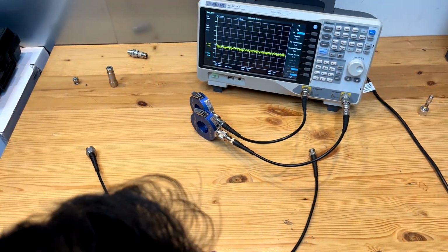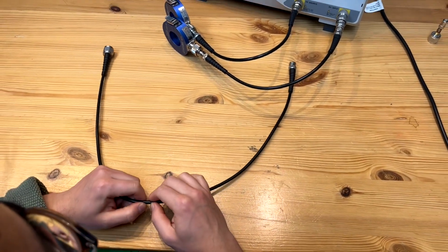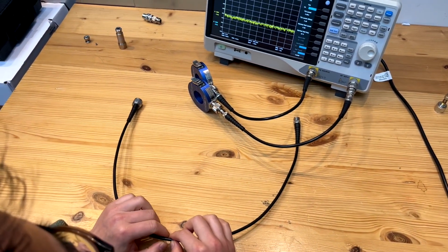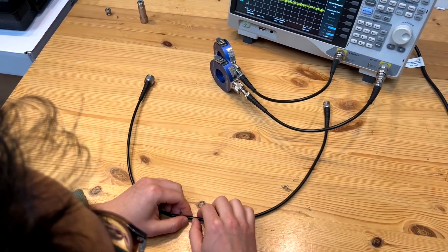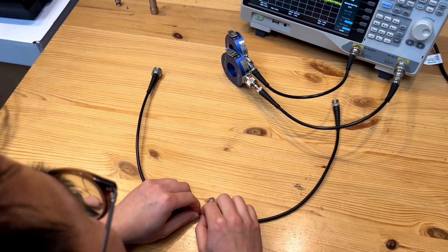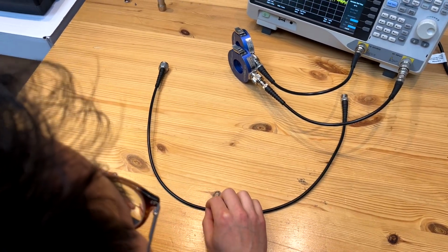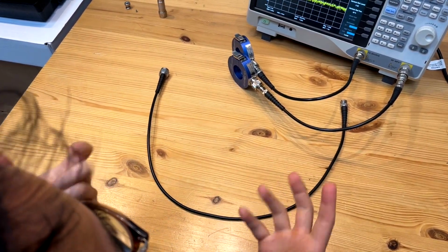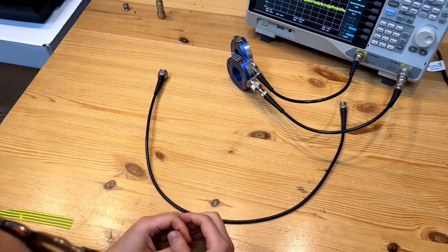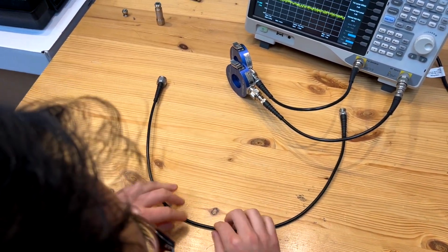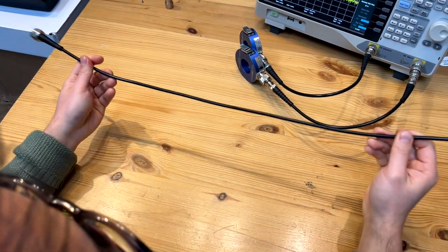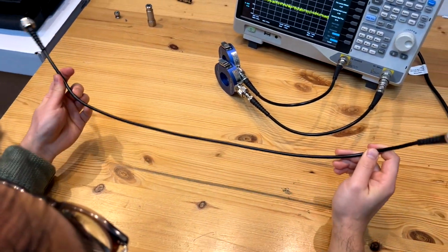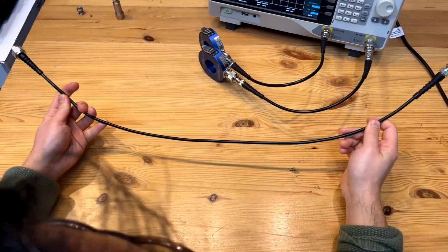But the middle point, the feeding point where I want to feed signals, has a relatively small impedance to earth, often about 70 or 80 ohm. So if I want to feed signals, obviously I want to choose a low impedance point. So this would be my feeding point. Then I can make this coaxial cable an efficient half wavelength antenna.